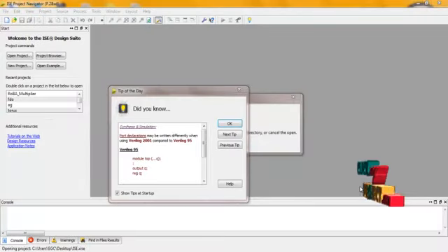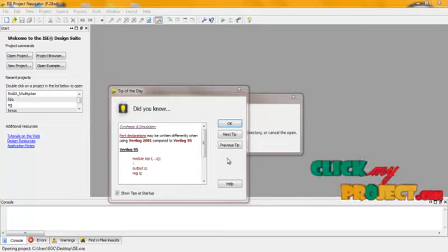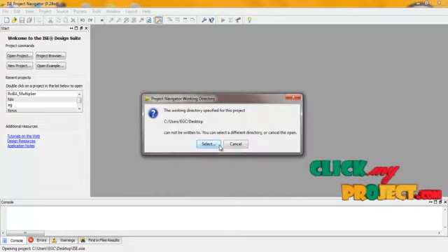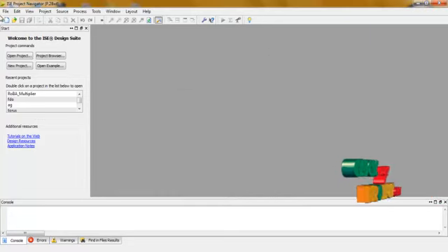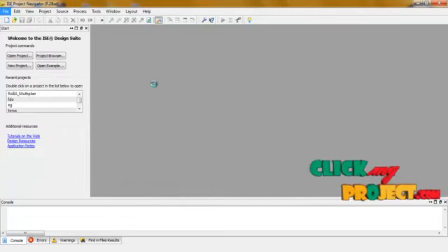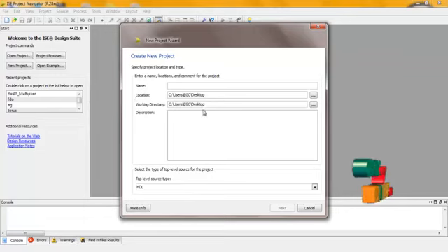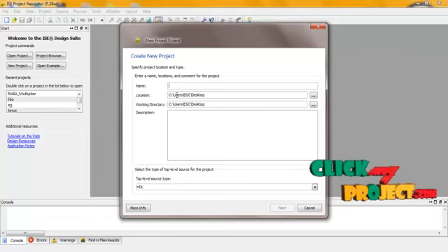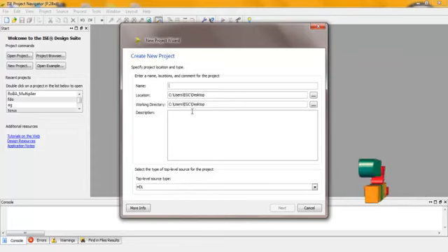Now we are going to discuss the running procedure of our product. Our product can be implemented using the Xilinx ISE Project Navigator tool. Double click to open the tool window and create a new project. Create a new project using the file option, File, New Project, in order to assign our design name using the name option, and the location in the location option.